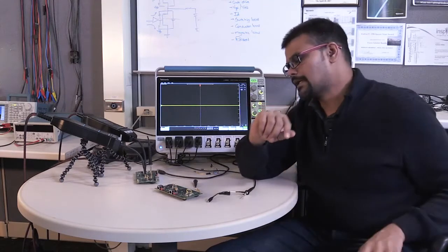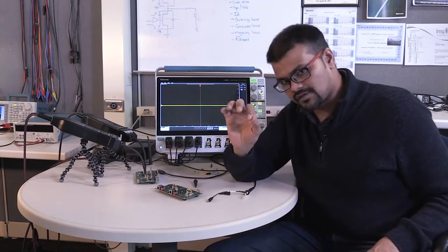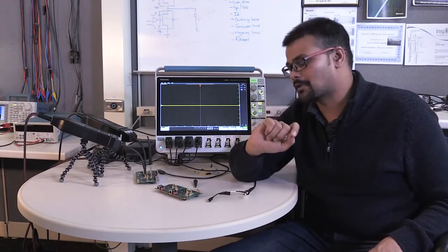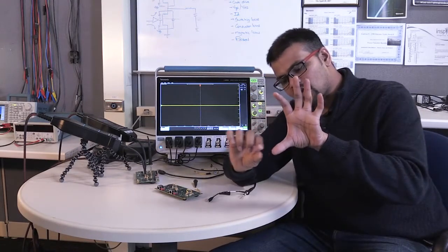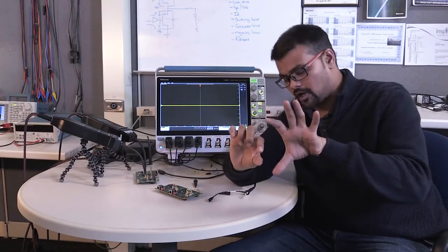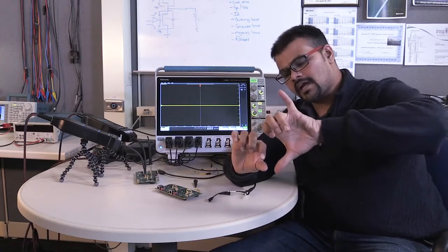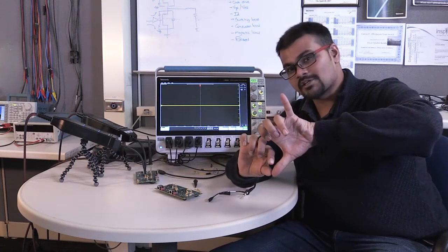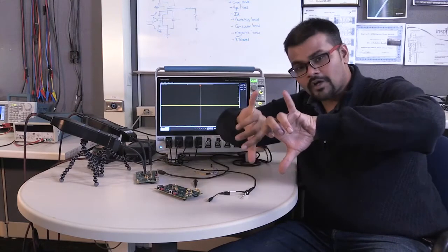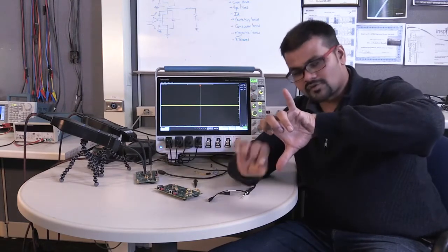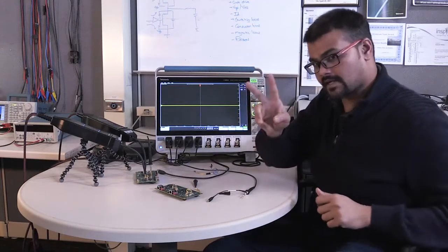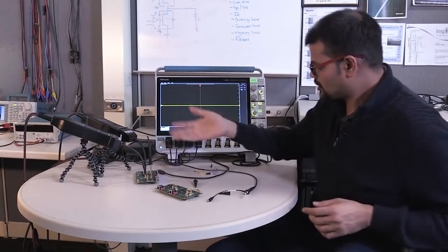I'll give you another example. Think about conduction losses, right, or switching losses, and think about the RDS(on) measurement, which is another hot one. The RDS(on) measurement is in the conduction area, which is really small, usually in millivolts, depending on your RDS(on), and you're looking at it in presence of a VDS measurement that can be 400 or 600 volts, right? So you really need the vertical resolution, the number of bits, to resolve that to get decent accuracy from that measurement, right? So 12 bits is the second reason, and the third reason is sheer number of channels, right?